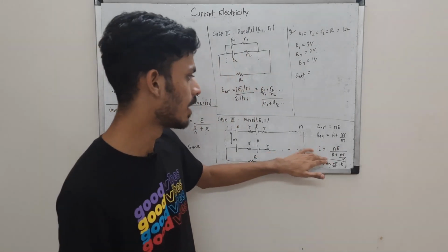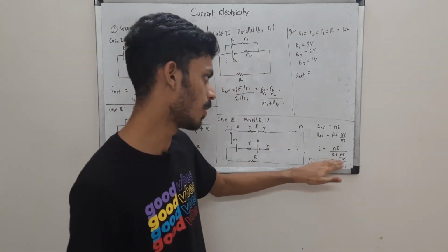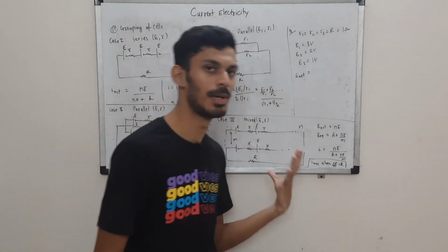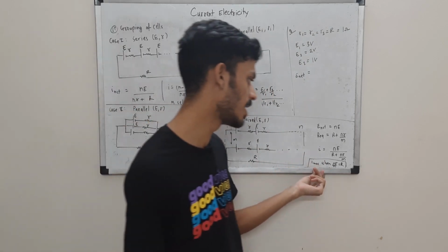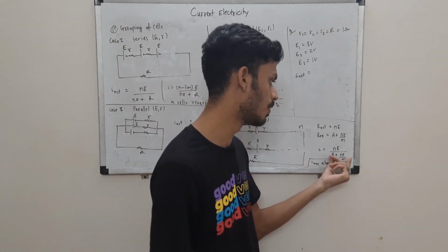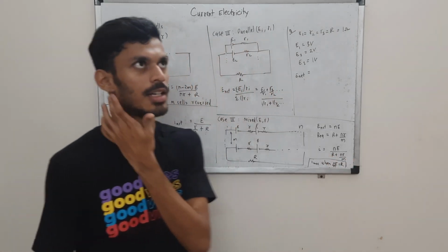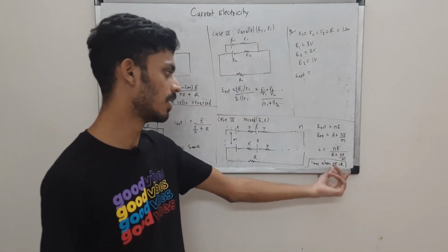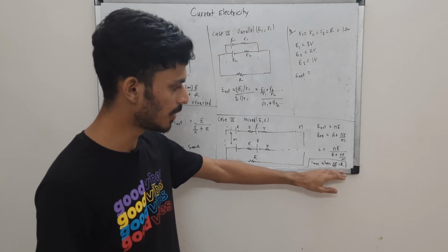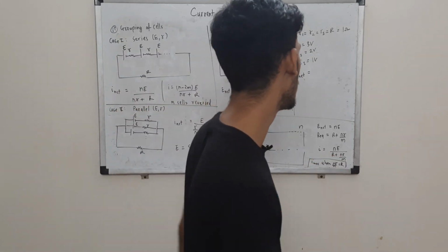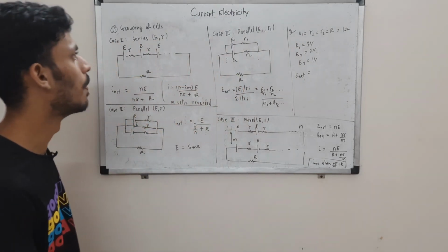Okay, I is now the net EMF divided by R equivalent, so that is I, and this will be maximum. The power delivered by the circuit will be maximum when I is maximum. When I is maximum, these two should be equal. This is a condition that we obtain from differentiating. We equate the first derivative to 0, and that gives us this condition. We'll speak about it more in the derivation class. So in this denominator, these two terms should be equal for current to be maximum.